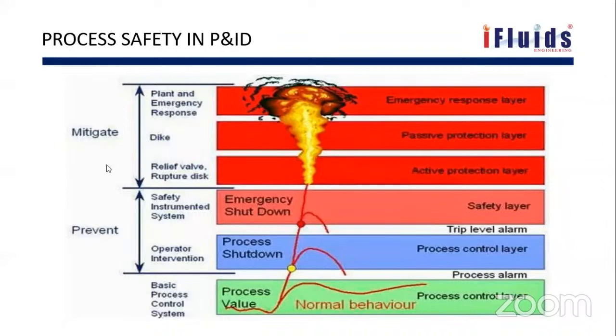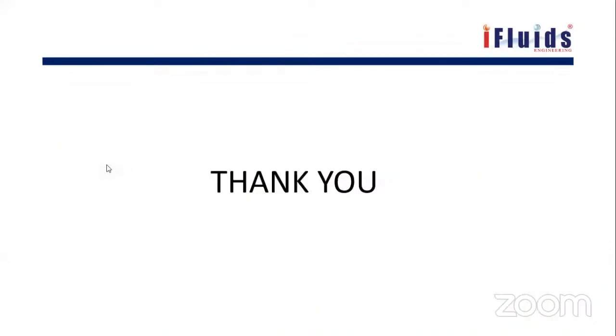Okay, so we have come to the end of that session. Hope you would have understood the concepts. So we'll just have a quick recap of what we learned today. We have learned different piping arrangements, especially isolation types, positive isolation and valve isolation. Positive isolation is given where equipment is to be handed over for maintenance or person enters into the equipment for inspection.